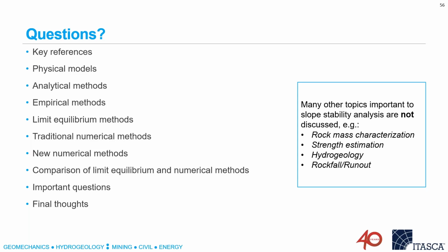And rather than testing rock which has 200 megapascals UCS and figuring out what its modulus is and its Poisson's ratio, we do need to spend our time and efforts looking for and characterizing the weakest parts. And these are very often faults, and very often they get ignored by people in the field, by people building models and so on. But because they are weak components, we must include them in our models in the best way possible.